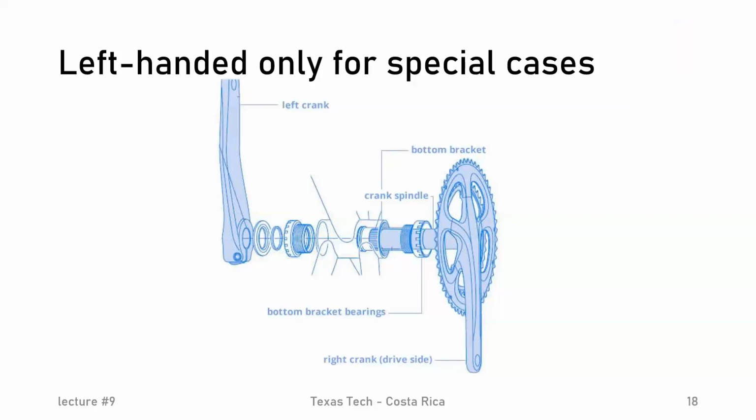Could very well be. But one thing where we see this all the time is in the crankshaft of a bicycle. And not so much directly in the crankshaft, but in the places where we attach the pedals to the crank arms. The reason for that is that we want to make sure that as I'm pedaling, I'm not loosening, right? If I had the lefty loosey on both sides, then as I'm pedaling, I would loosen one of them all the time, and the pedal will keep on falling off. So that's why we have one that's the opposite direction.